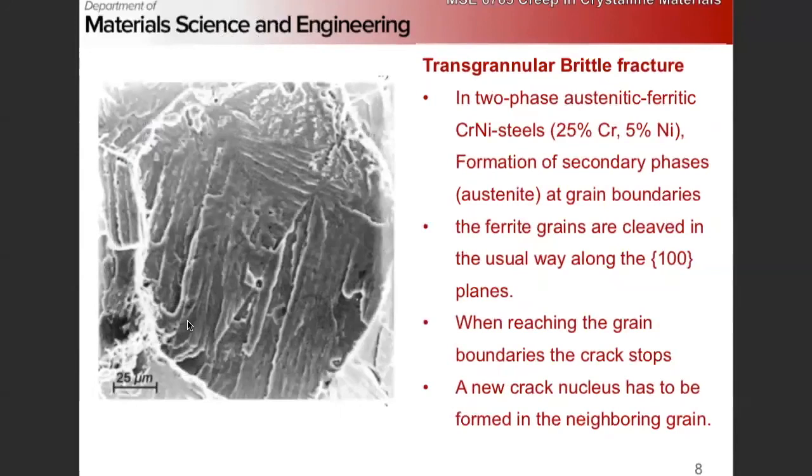So there's a lot going on in the figures, and it's made more complicated by the mechanism, right? The mechanism to get the austenite in these steels is kind of confusing because you get delta iron that forms, which then decomposes at a lower temperature to austenite. Right. So to interpret these, you have to know a whole lot about the metallurgy of your system.